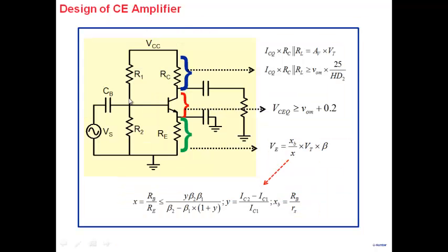And in this context, this was an important picture here. The supply voltage in this case is limited, and you have to allocate it. Part of it you may allocate to gain and swing. Gain here depends on this part here. This part here depends on the swing. And this part here decides the stability of the bias point. All right. So in most cases, you will find that in a design there is a resource which is precious, and there are multiple demands on that particular precious resource, and you have to allocate, you have to budget. So this is showing the supply voltage in this case is a precious resource. There are multiple demands on the supply voltage here, and how do you allocate? Allocation of this one here.